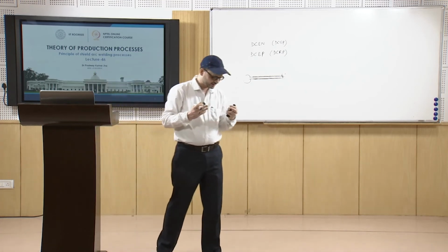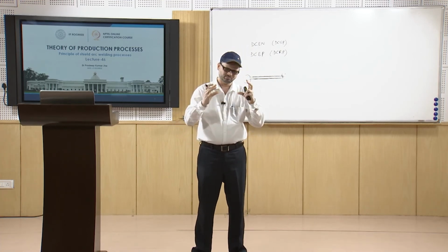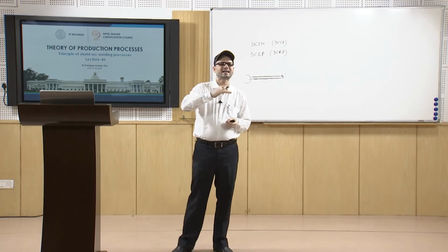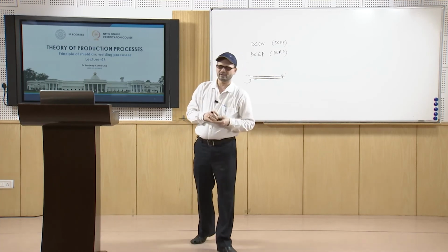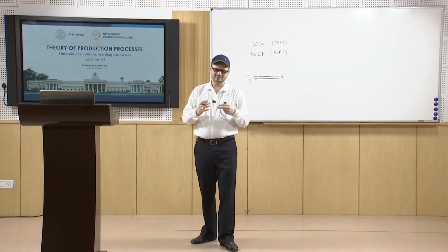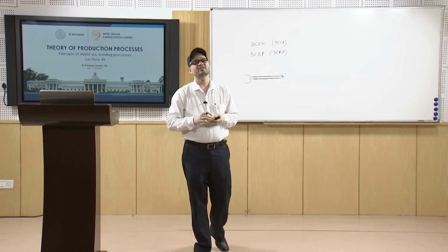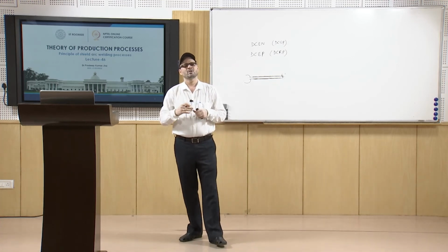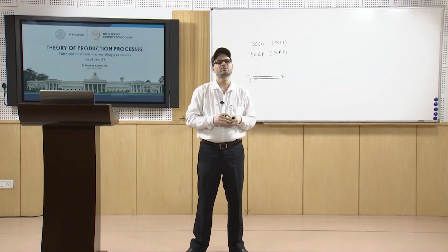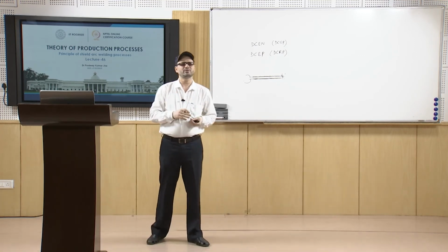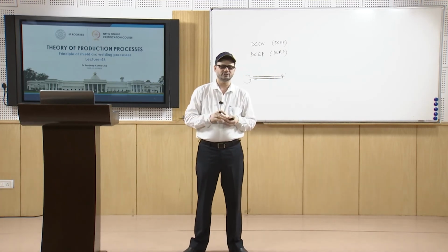Another limitation in shielded metal arc welding is that you have the making of flux, and these fluxes, being lighter, are at the top surface of the weld. That has to be removed in every pass. If you do not remove it, it may create problems, forming undesirable phases that may affect the corrosion resistance or other mechanical properties of the material. So these are the limitations of this process.